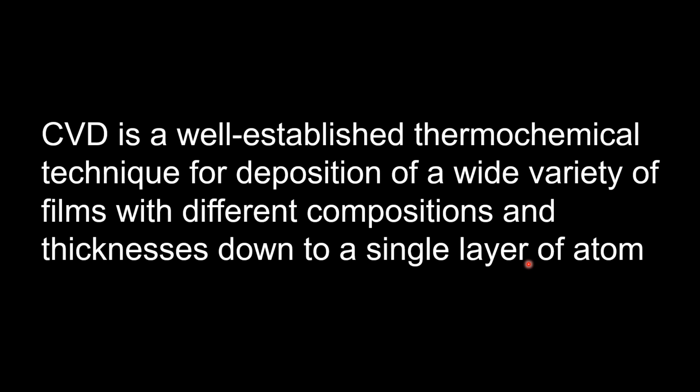Thermochemical means a process in which a reactant reacts on the surface of a substrate due to heat, and due to the thermochemical reaction you can deposit ultra thin films in the range of a few atoms, thin films in the range of a few hundred nanometers, and even thicker films which may be in the range of a few hundred micrometers.